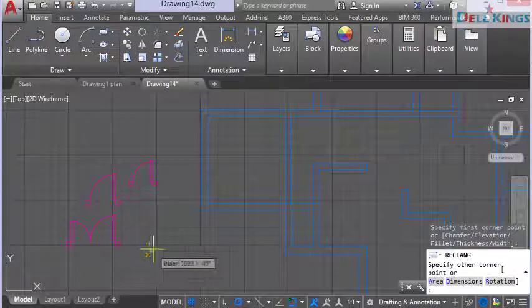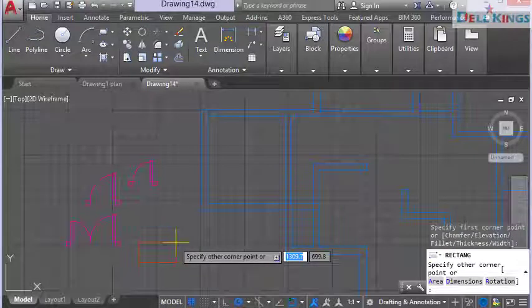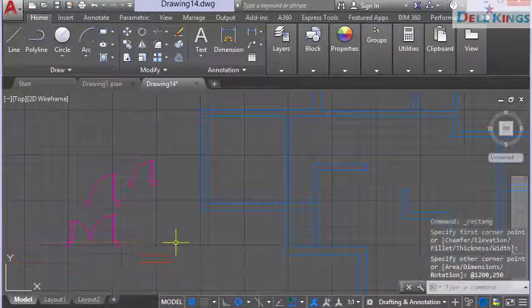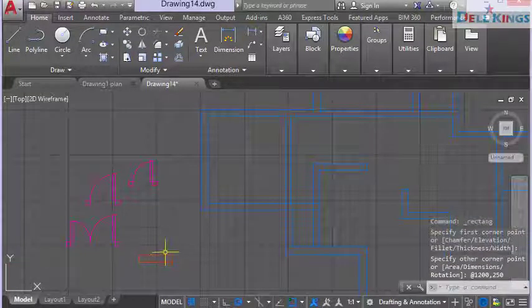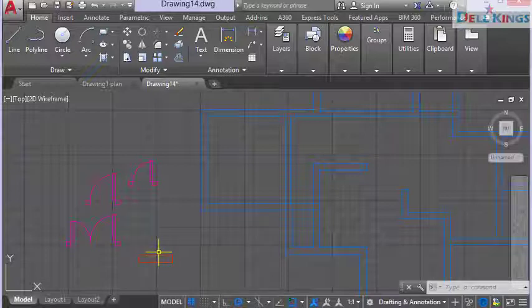So at this point I'll start my drawing, and I'll input the dimensions of 1200, 250, which is the wall thickness for the outer window. So press enter, and we have this window here. So next we'll explode this rectangle so that we offset these 2 up lines here.